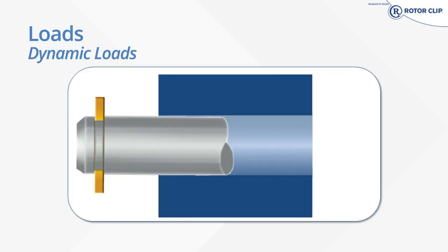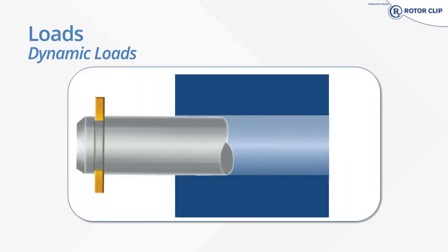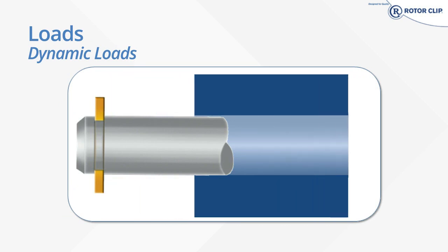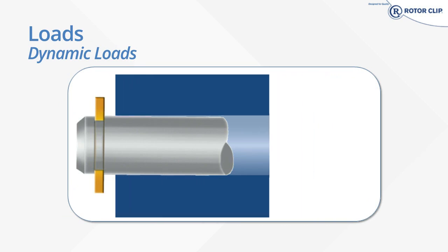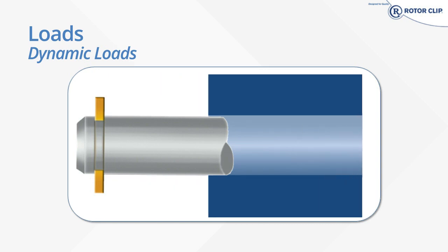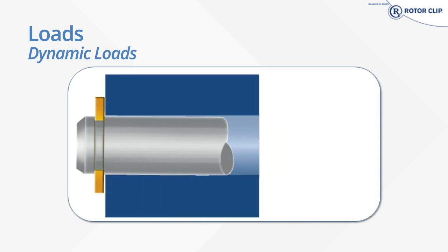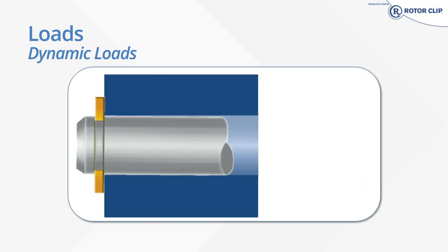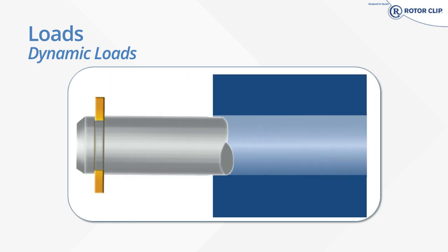Dynamic loads, so punching the table. There's 2 types of dynamic loads, sudden loads and impact loads. Sudden loads occur when a surge in thrust load is transmitted to a ring installed tightly in an assembly. In this scenario, there is no play between the ring and the retained part. The sudden load should not exceed 50% of the allowable static load, PR or PG, whichever is lower.